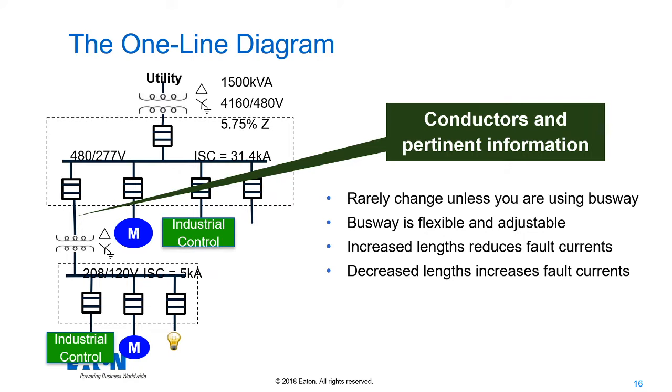And the same goes with transformers. Since we haven't bought a transformer yet, on a drawing in a bid package or something of that nature you'll have the kVA, you'll know the voltage, but you're not really going to know the percent impedance.